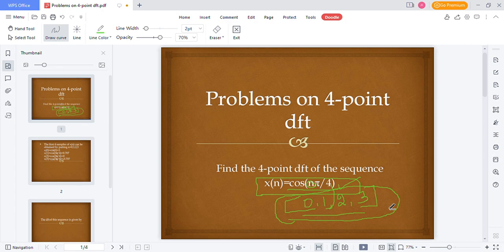And there is no certain set of procedure that you have to follow for those particular problems. You're going to solve according to how the problem is given. If you want to shift a takeoff point behind the block, you do that. Or first, if you want to eliminate blocks in parallel or in series, or eliminate the minor feedback loop, you do it according to the given problem.